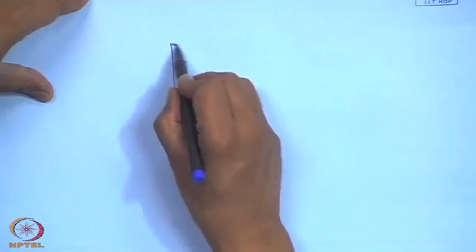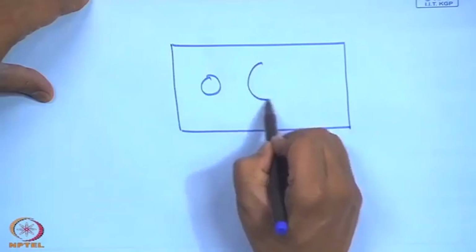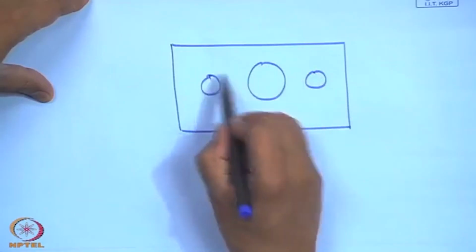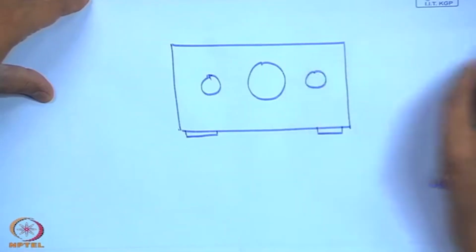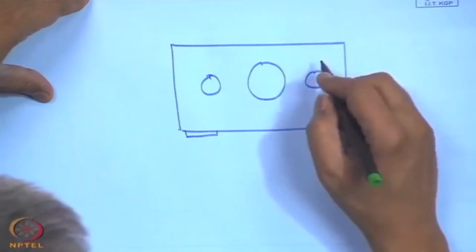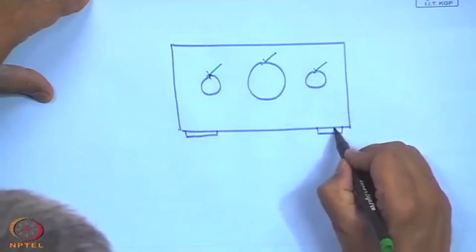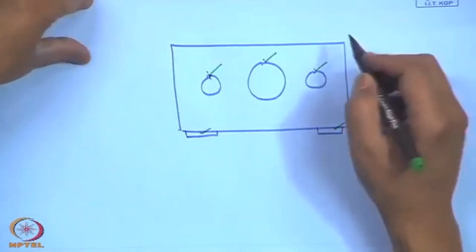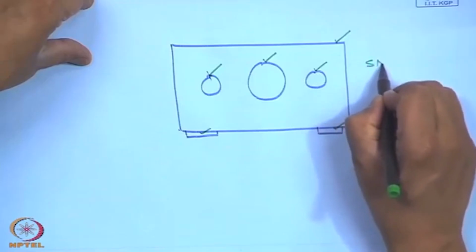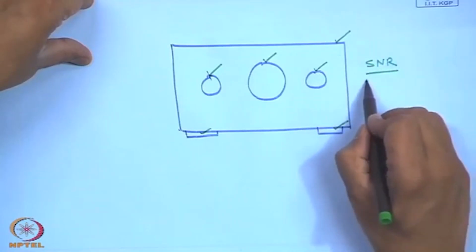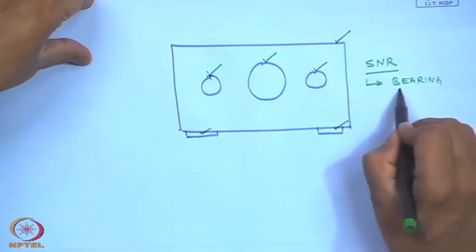How do we capture the gearbox vibrations? Suppose I have a multi-stage gearbox; from the outside, these are the bearing housings, and these are the bases of the gearbox. Usually, the good locations to put the transducers are at the bearing locations. Sometimes we put one on the base just to make sure, and just for reference we can put it on one casing. Of course, the highest signal to noise ratio will be obtained at the bearing location.